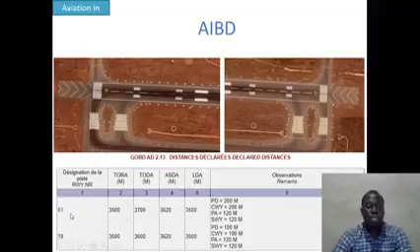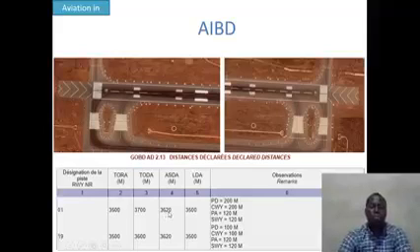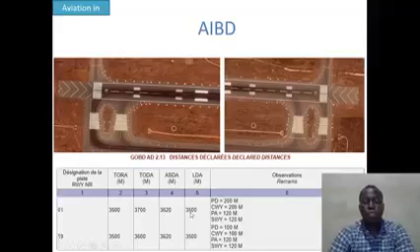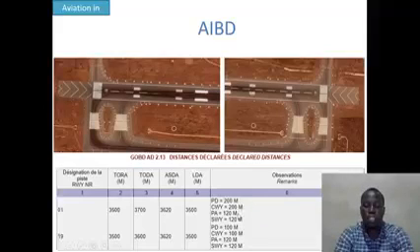You see for the runway 01, the TORA is 2,500 meters, the ASDA 2,700 meters, the TODA 2,620 meters, and the LDA 3,500 meters, knowing that the clearway is 200 meters and the stopway 120 meters.